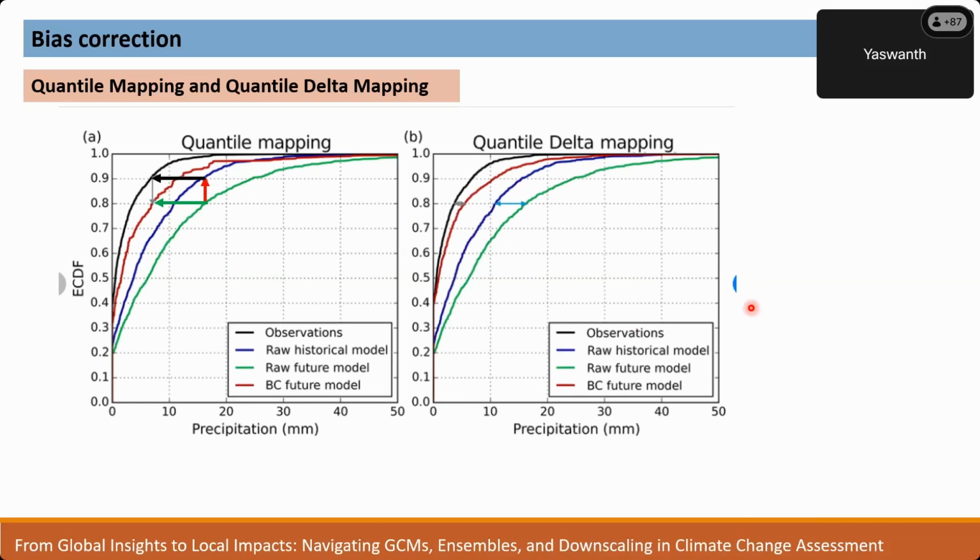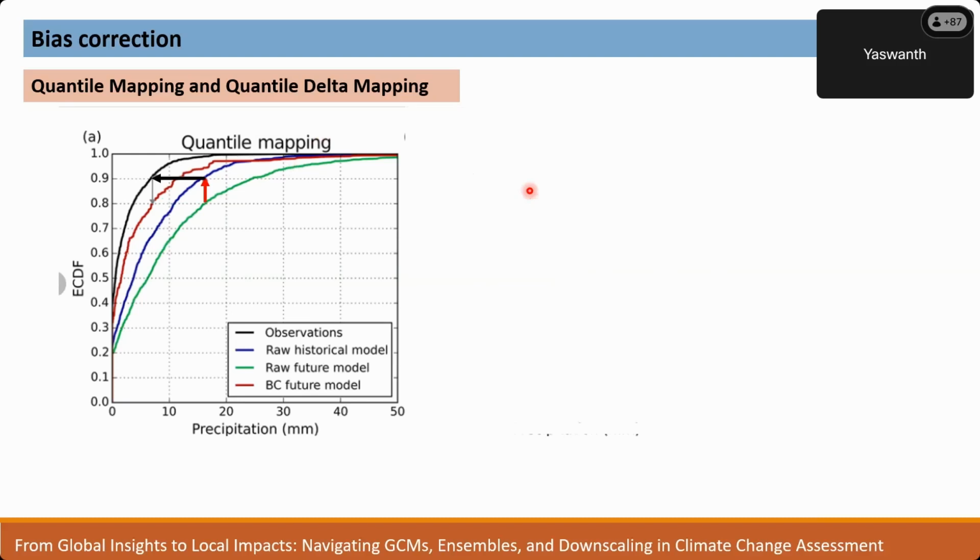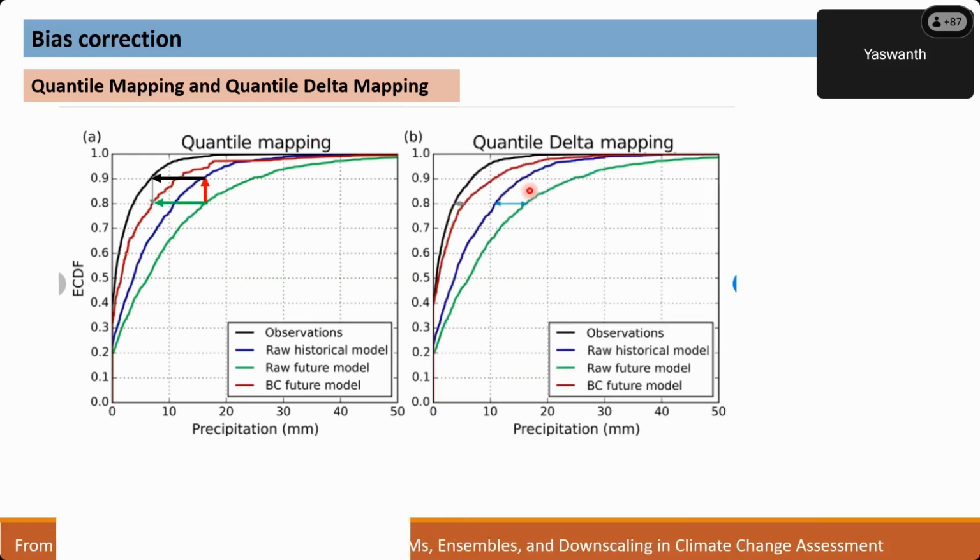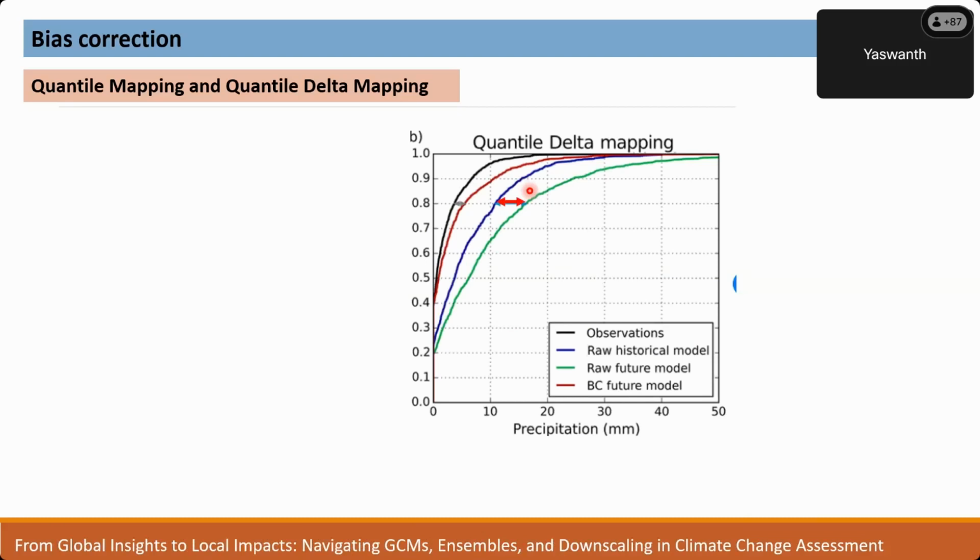But what recent researchers have found, around 6 to 7 years back, is that quantile mapping, which is very, very widely applied, has an inflation issue. It can artificially corrupt the trends that are happening in the models. If the model is showing a 20% positive trend, because of quantile mapping, the inherent algorithm is showing a 40% to 50% higher trend after corrections, which is not actually shown by the GCMs. So they suggested that it is better to use quantile delta mapping rather than quantile mapping, which corrects at the same quantile levels instead of going for the upper region values.